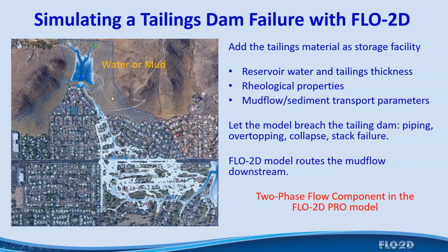So if you decide to go that way, you will need to enter the tailings dam material into your FLO-2D domain, and assigning that tailings dam material to the domain, you will need to also enter some data regarding the tailings dam material and the reservoir water, the tailings thickness.